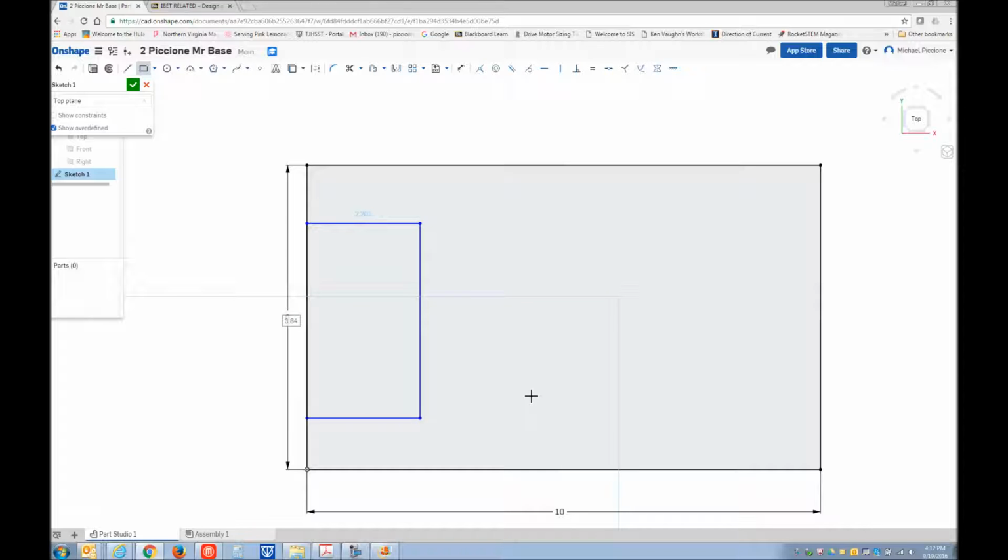I'm going to do the same on the other side, except I'm going to first track from this intersection and then make sure this far right line is highlighted as well. And notice now I have 2 constraints showing up on my screen. I have a horizontal constraint with the dot we connected to on the one side, and a coincident constraint for the line we're currently on.